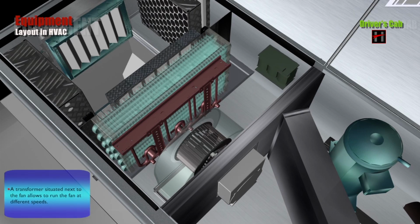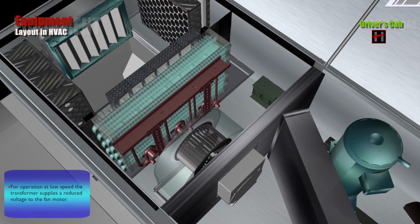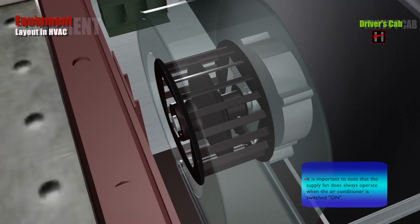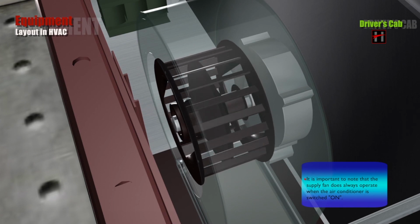A transformer situated next to the fan allows to run the fan at different speeds. For high-speed operation, the fan motor is directly supplied with 415 volts. For operation at low speed, the transformer supplies a reduced voltage to the fan motor. It is important to note that the supply fan does always operate when the air conditioner is switched on.